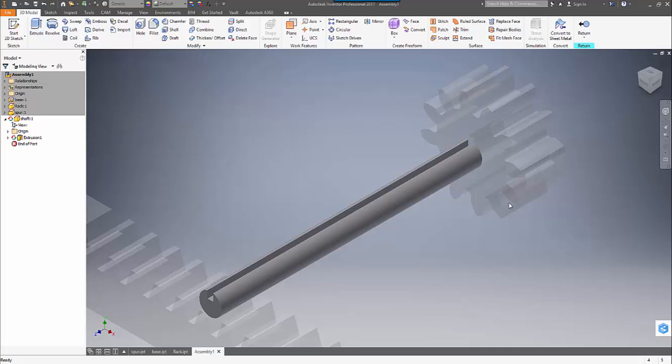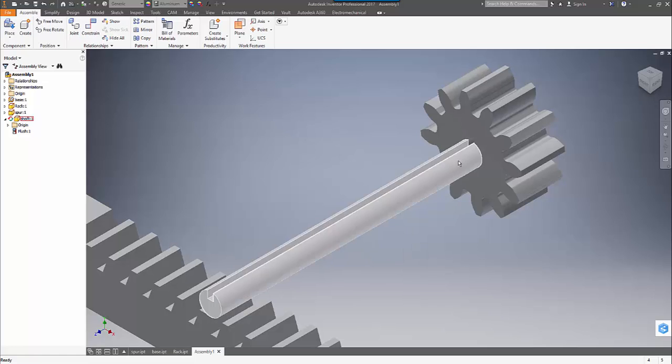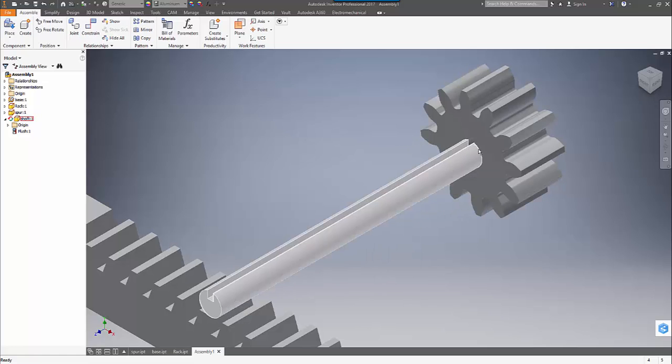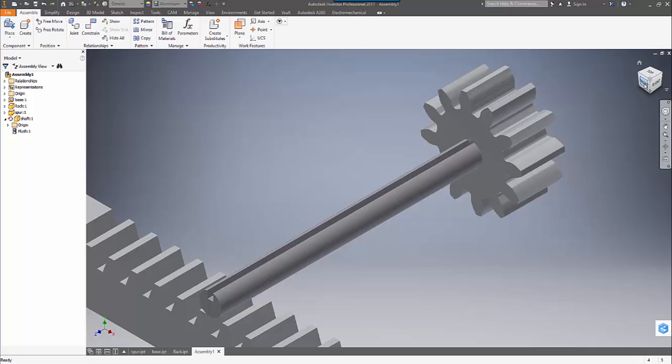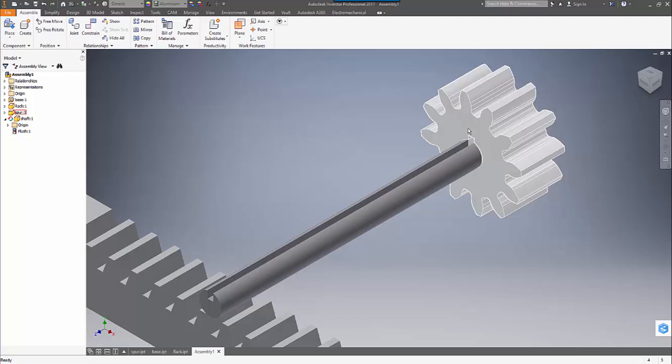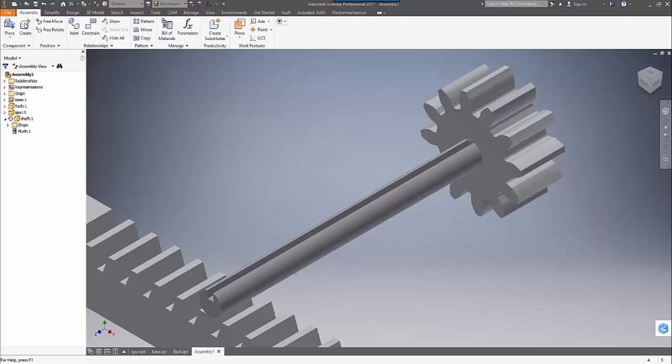And that should be enough. And if it isn't, we can always go back and update it. So we now created the shaft itself, and we'll return out. So now we have to create another part, and that's going to be the key for the keyway. And what's nice is that I can use the end of the shaft, or I can go back and use the spur surface as the basis to create that key, or the key itself.